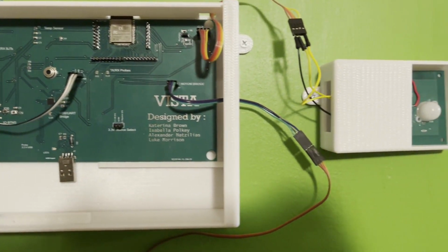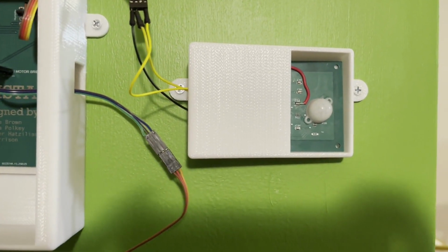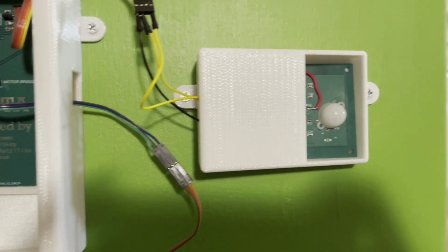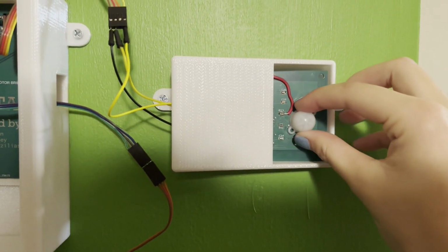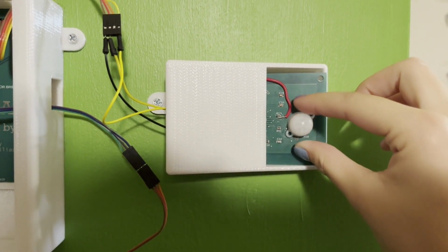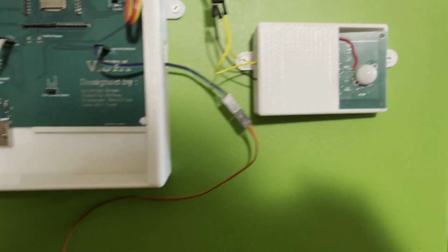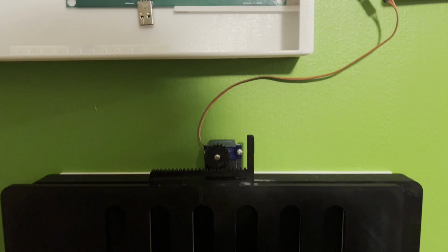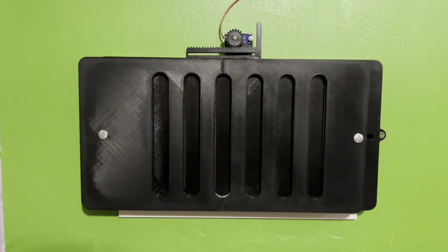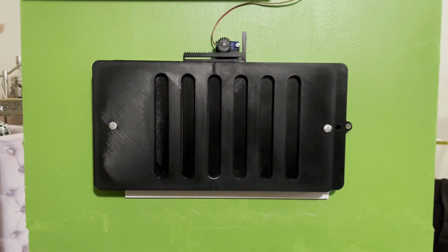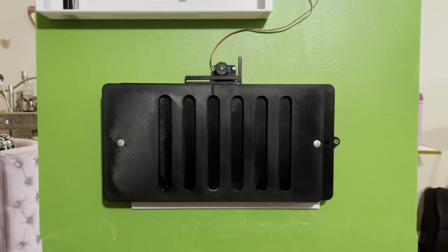The occupancy sensor is its own PCB that has a separate housing structure. The idea behind this design is that the occupancy sensor can be tilted as needed in a given space in order for the lens to view an entire room. Once the ESP32 receives data from the sensors, the information is used to power a servo. This servo works in conjunction with a rack and pinion system that converts the rotational motion to linear.